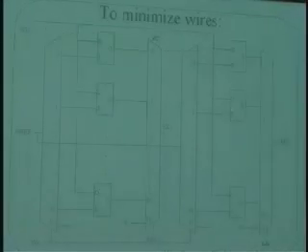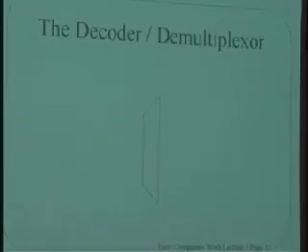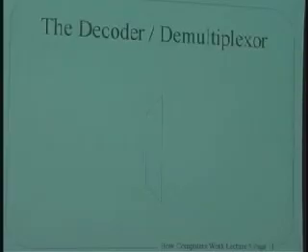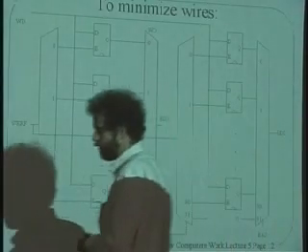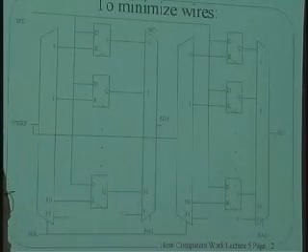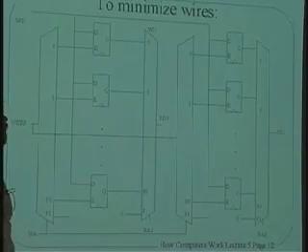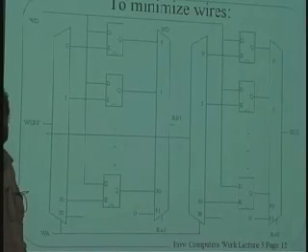So we need to understand how this thing works, this decoder. It's also called a demultiplexer, the same way the other one is called a multiplexer. And I basically told you how it worked, how it took an input and chose the different outputs. Turns out you could implement this a slightly different way. And there were computers like the, I know the PDP-11 did this, I think the VAX did this too. This was a standard trick, I think DEC even had a patent on this, for how to lower the number of wires that crisscross across the register file.